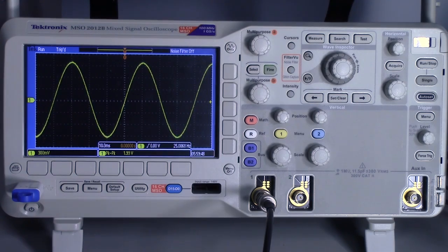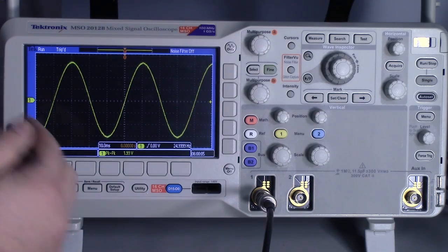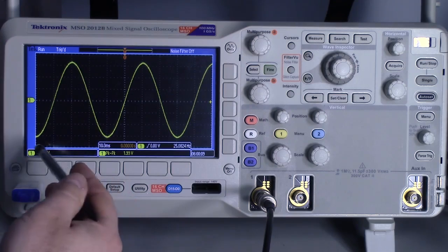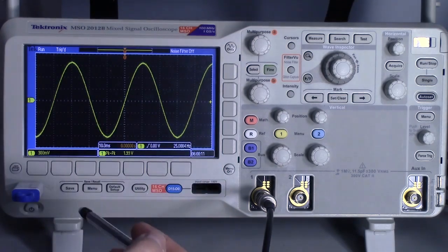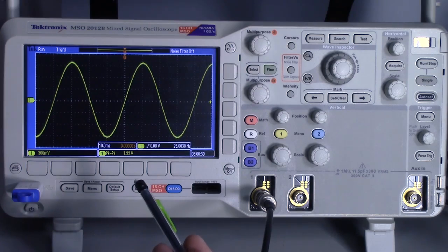So with electronics, we need instruments to actually connect to and see the signals. And the oscilloscope is one of the most important instruments that you'll use in electronics. Fundamentally, all it does is measure voltage over time. So voltage is going to be your vertical scale, and the horizontal will be time. Now the oscilloscope is going to be used primarily for high frequency, for small time periods.